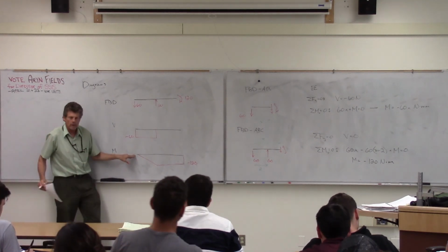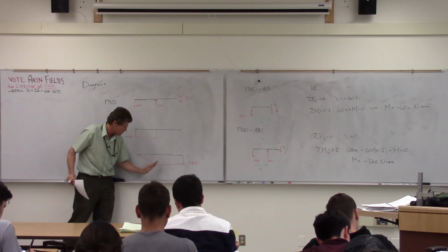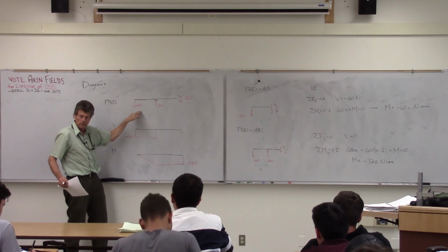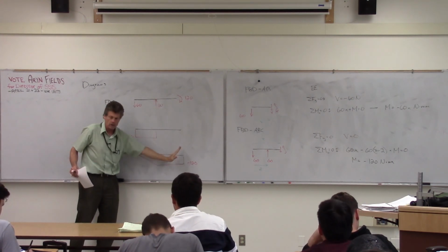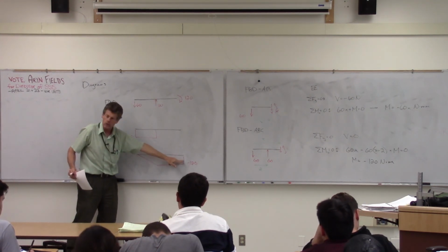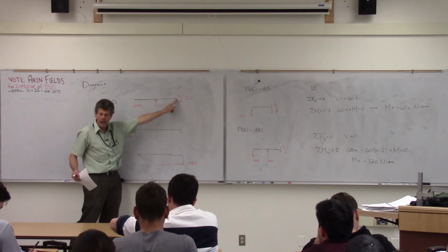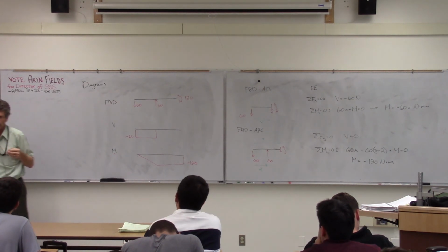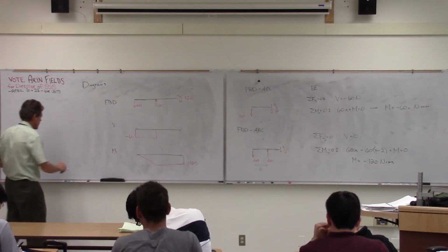So the moment diagram, as we saw, changes by that x. And then once it gets here, that couple kicks in. Now it's a fixed couple, right? So when we get past that, then it's going to stay the same. And again, we see a jump now at the free end of 120 because there is that concentrated twist at the end. So that's where I wanted to show you that.